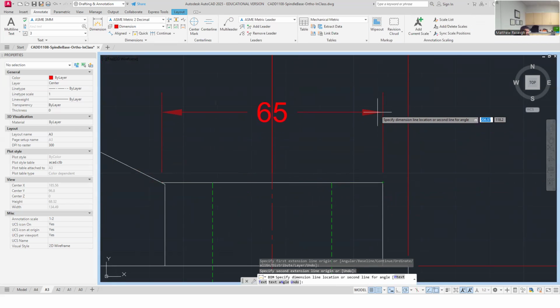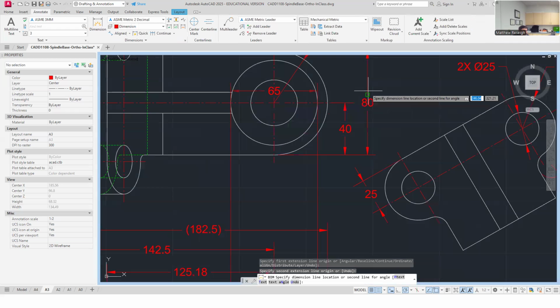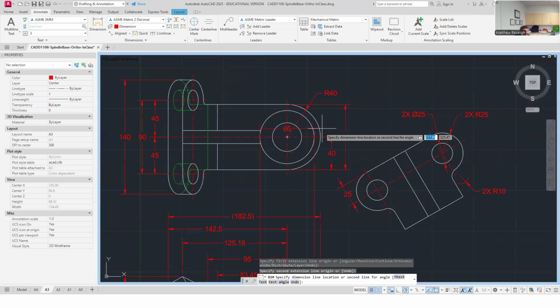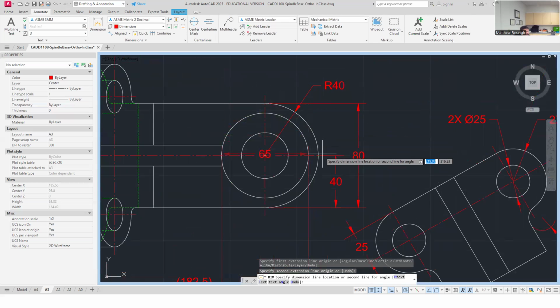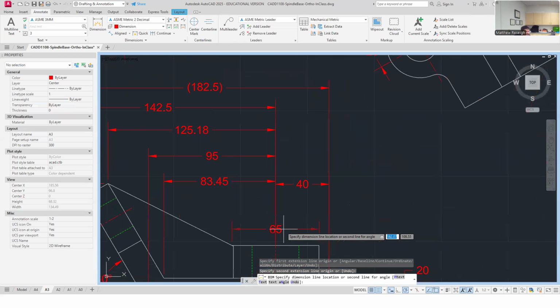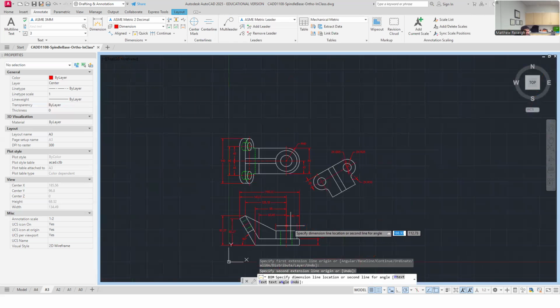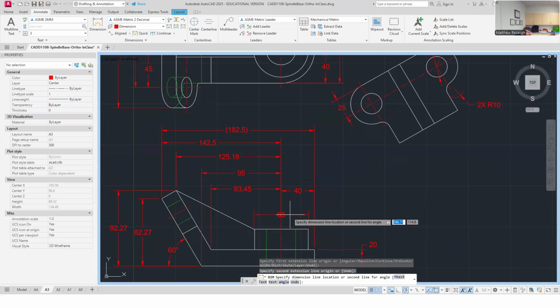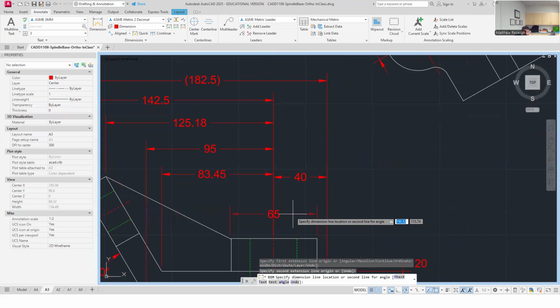I caught a few people on prints doing that, and that's an easy thing to confuse. Like, why wouldn't I do the diameter of a radius where it appears like this? Like this 80, should I put a diameter sign in this? No, we're talking about a radius of 40 is the better description of the outer profile, not a diameter of 80. 80 is kind of the depth across the rectangular surfaces. So that's easy to confuse, I think, when it's a radius part that I would want to put the radius, not a diameter in its rectangular view.